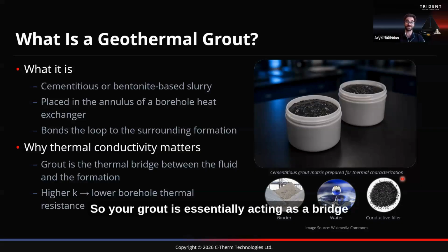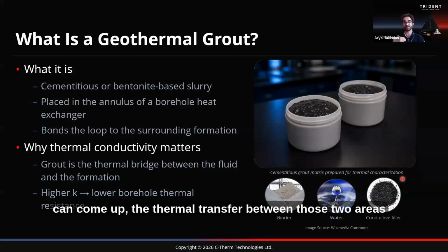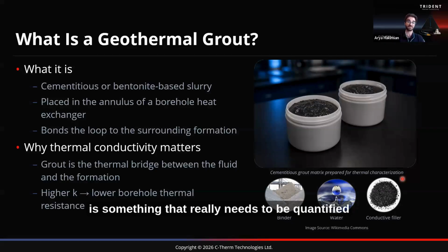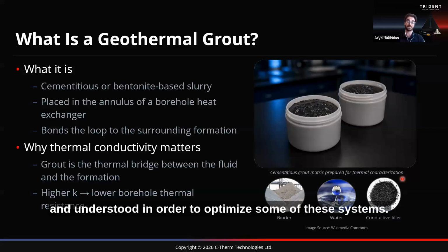So your grout is essentially acting as a bridge between the fluid and the formation. Looking at where bottlenecks can come up, the thermal transfer between those two areas is something that really needs to be quantified and understood in order to optimize some of these systems.